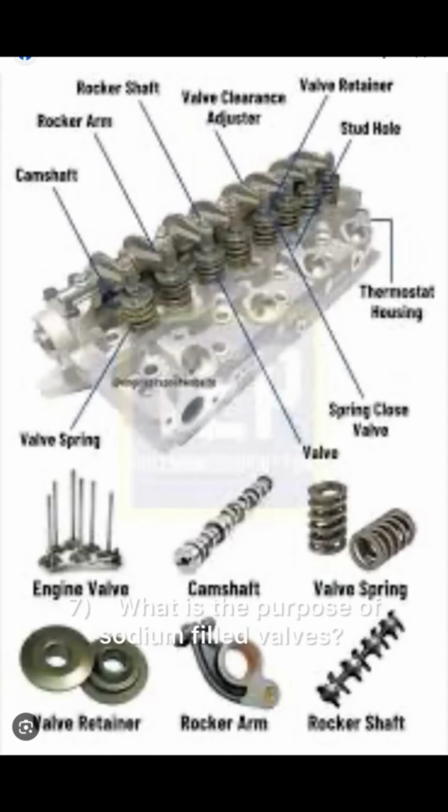7. What is the purpose of sodium-filled valves? To transfer heat from the valve stem to guide more efficiently. Valve will run about 15% cooler than a solid-stemmed valve. Heavy-duty applications or where more cooling is required. 8. Identify the following terms. 1. Valve tip. The upper end of the valve that is in contact with the valve operating mechanism. 2. Valve keepers. Hold the spring retainer on the valve. 3. Valve stem. A machined part of the valve that extends from the neck to the tip of the valve.